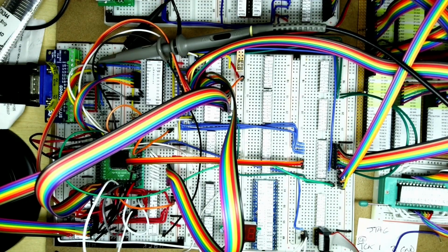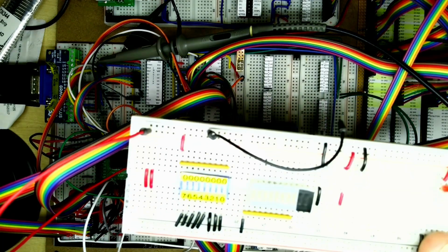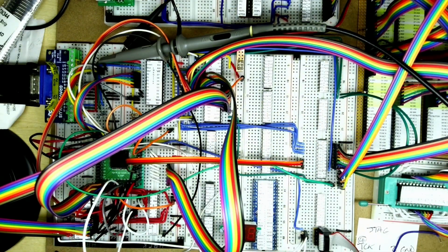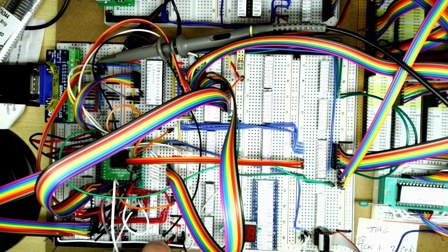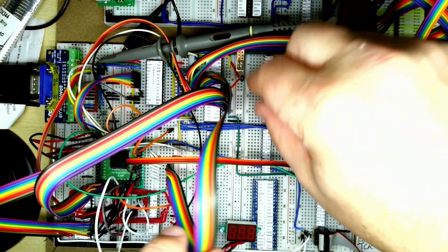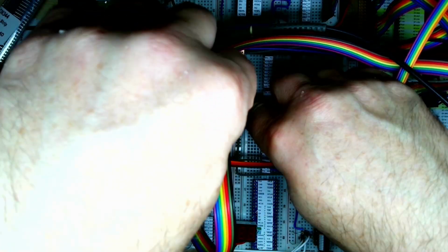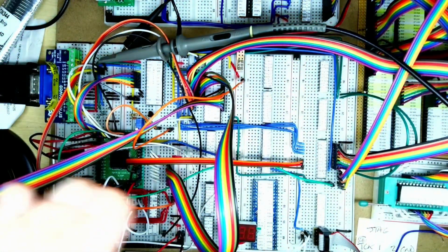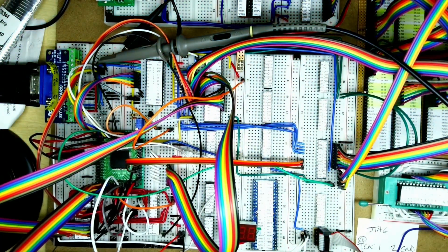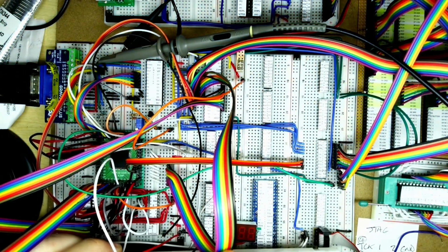What I might just do, in fact, is I have got this test board here. So rather than plugging in the attributes into the output of the CRTC, I might just plug it into this board, and it means I can then just vary the inputs by the dip switches, so I can actually go through all the colours individually. Might be a little bit easier to see what's going on. So I'm just going to take the attributes out of there and plug it into this little board just down here.